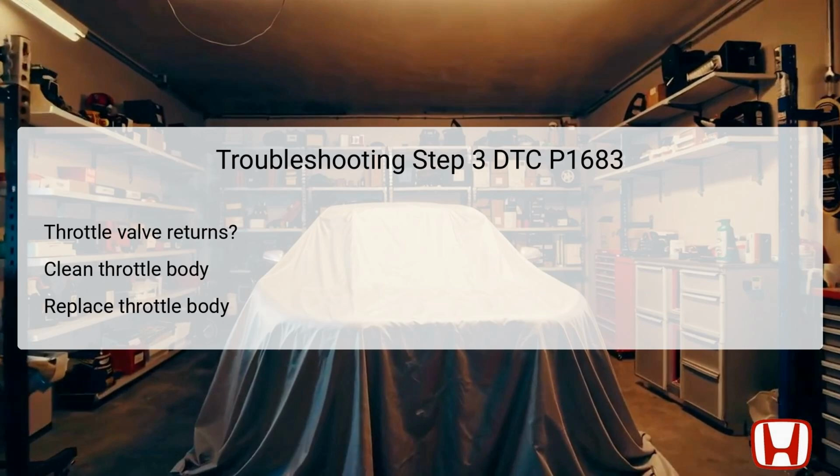If the throttle valve successfully returns, then the technician should proceed to clean the throttle body. Cleaning can often resolve issues related to carbon buildup and other contaminants that may affect the throttle valve's operation. Following the cleaning, the technician should conduct repair verification to ensure that the cleaning successfully resolved the DTC.